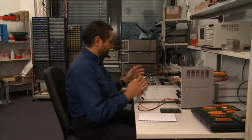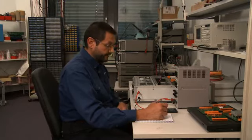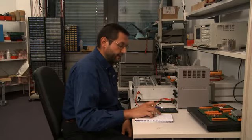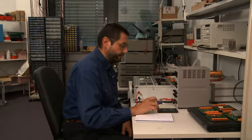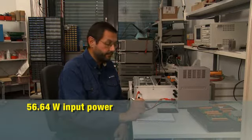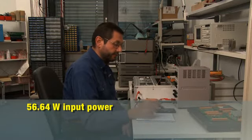Then we can read the final temperature, and then we can calculate the thermal characteristics of the system. Now that we have collected all the experimental data, we can complete our calculations and verify the thermal characteristics of our system. The input power to the system can be calculated by multiplying the input voltage by the input current. So we have 24 volt input multiplied by 2.36 amps gives us 56.64 watt input power.